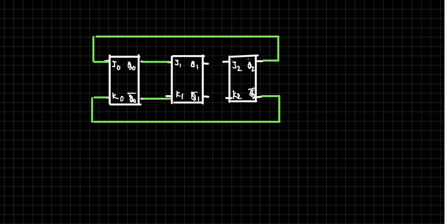This is again a ring counter using JK. What if I interchange, if I give the complement to the J input and the uncomplemented output to the K input, that becomes again a twisted ring counter. Okay. Homework for you is to verify the states. Now in the twisted ring, assume that the states are reset to 0 0 0 0 and then analyze the circuit and so on.